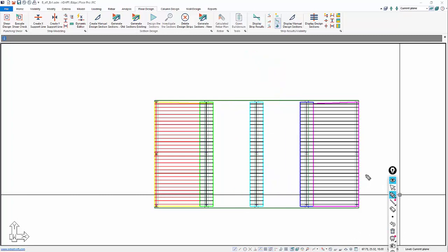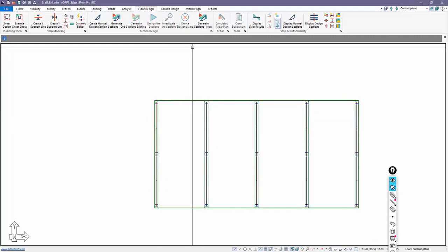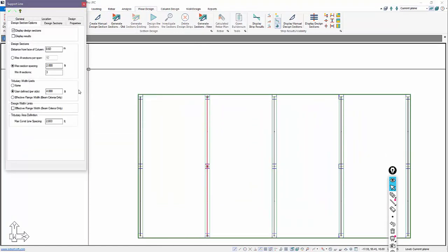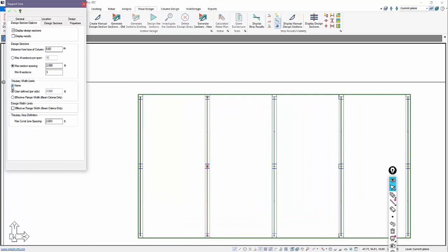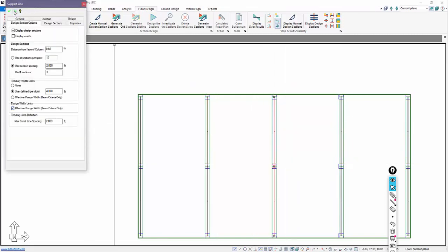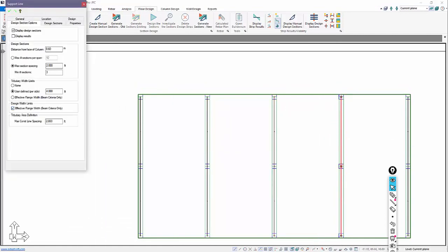Now another new option is the capability again of the program to calculate the effective flange for us. So if we go to these design strips again, these support lines, I'm going to set this back to none. I want it to integrate over the full tributary, but I want to limit the design width to the effective flange. Okay, and that's the setting here we'll check in this last run. We'll do that for these 3 interior beams.